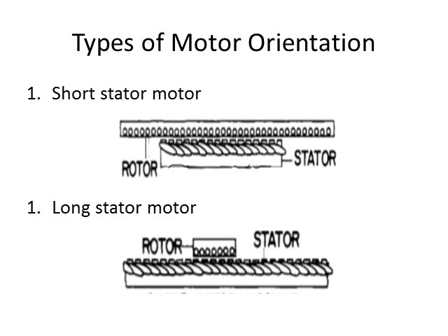The power source must be on the vehicle, and we might even have to perform cable management, which is a separate problem. The long stator motor is when the stator is on the guideway and must be energized from a power supply as suitable, while the vehicle has no such requirements, consisting only of the reaction plate or the magnetic array.